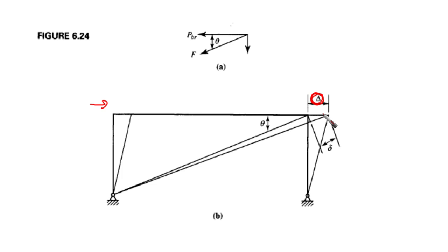This capital delta is going to be used to calculate the longitudinal, or axial, small delta here. From here we can make a relation based on the axial stiffness of the diagonal member, and then obtain the area required.